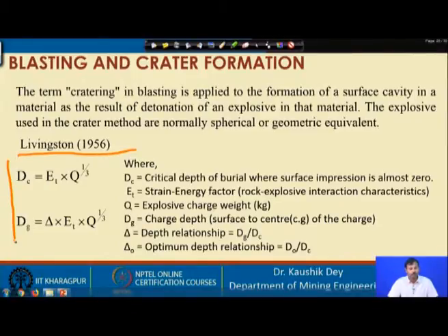The explosives used in the crater method are normally spherical or geometrically equivalent. So, the first condition of crater experimentation is that it must be a spherical charge. In this context, let me explain what a spherical charge is. A spherical charge is considered where the L by D ratio is less than or equal to 6.